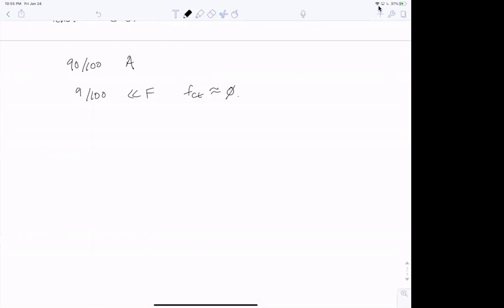So that means whenever there's tension in a concrete member, it won't work. To overcome that, we use steel. So steel is good in compression and tension. Concrete is good in compression only. And so the whole strategy of reinforced concrete is wherever there's tension, you would put steel.